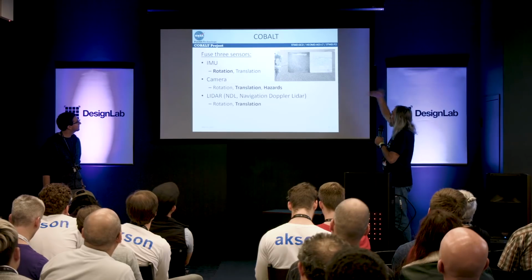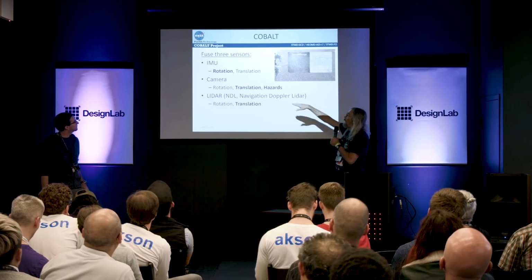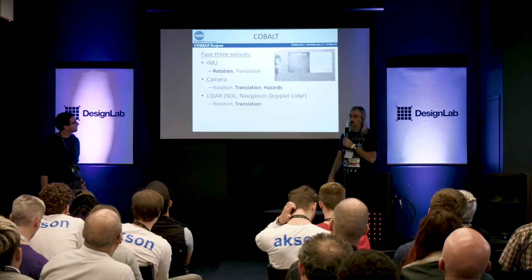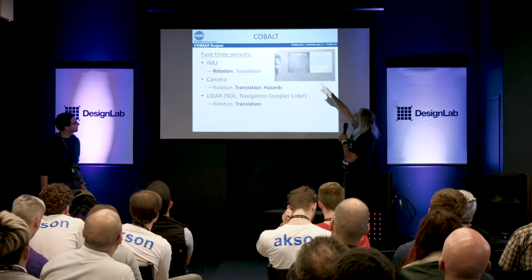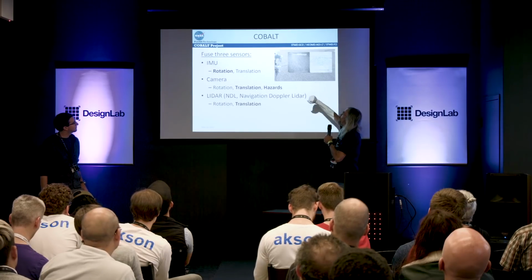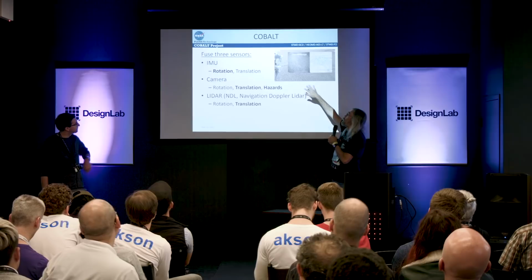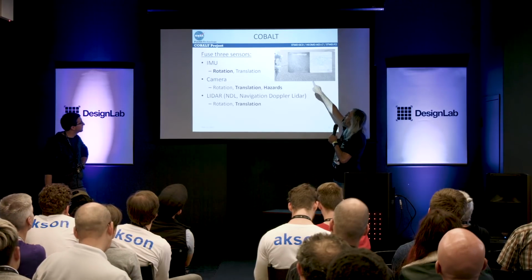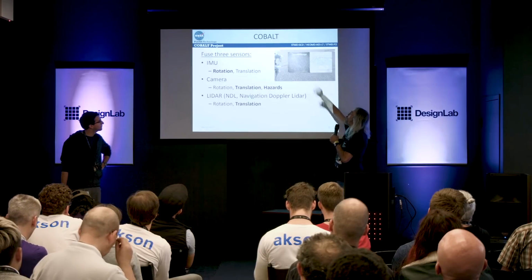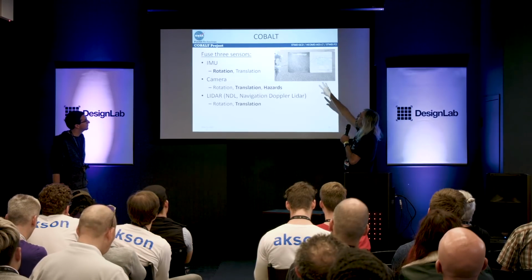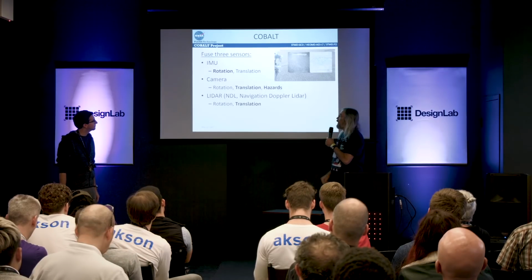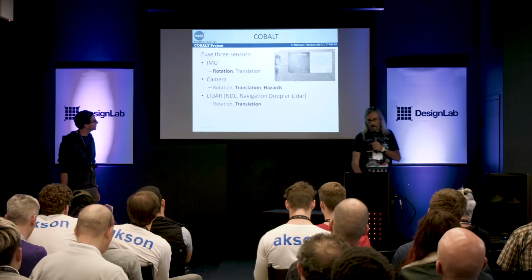Basically we're integrating an IMU and a camera that takes these pictures that let us do this localization. You can see from an earlier technology development program that was part of building LVS, pictures of the desert, and there's little green landmarks that have been picked out of the image, and they've been found on this onboard map to let us localize. And like I said, for Cobalt, we're going to add this LiDAR.